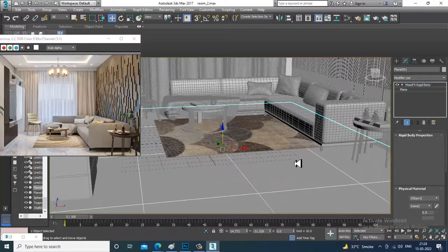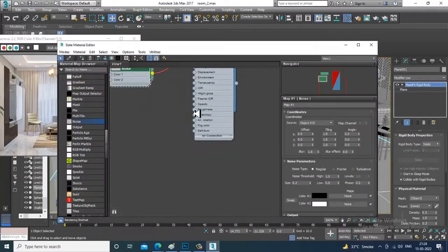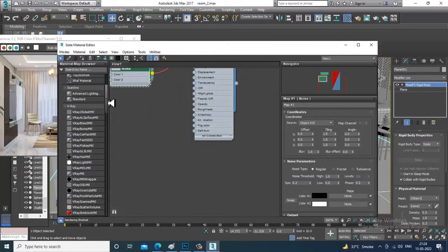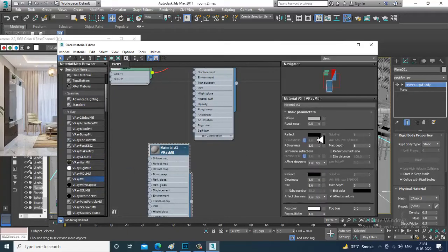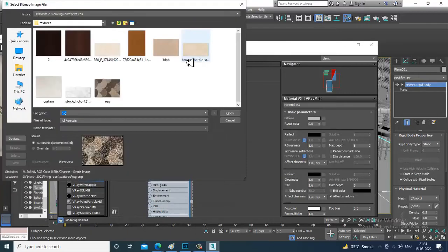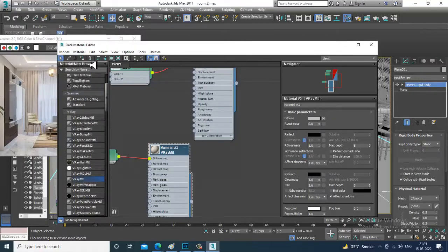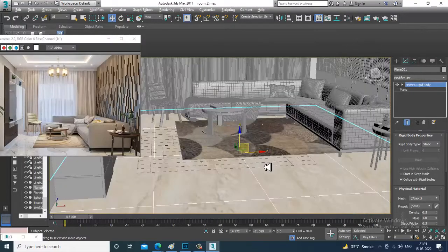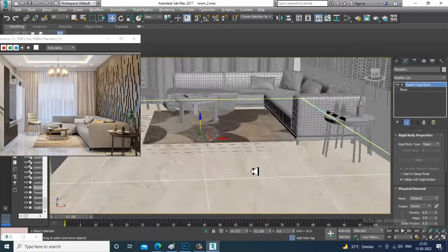Select this flooring section. Again go into this Vray material. So unwrapping is not required. If it is required, we can do it for a few of the things. So let's go into this and I can assign, I have different textures for it. I can also use this, that's a brown marble texture over here. I think looks much better.